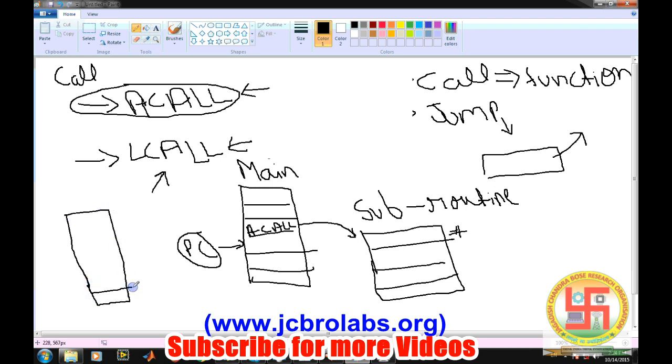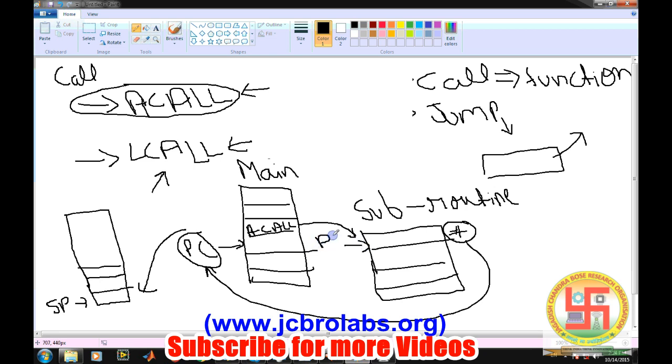So what does the computer do? The computer stores the current address of the program counter on the stack and then loads the new address into the program counter. So now the program counter starts pointing here, and the control starts executing the instructions from there onwards.